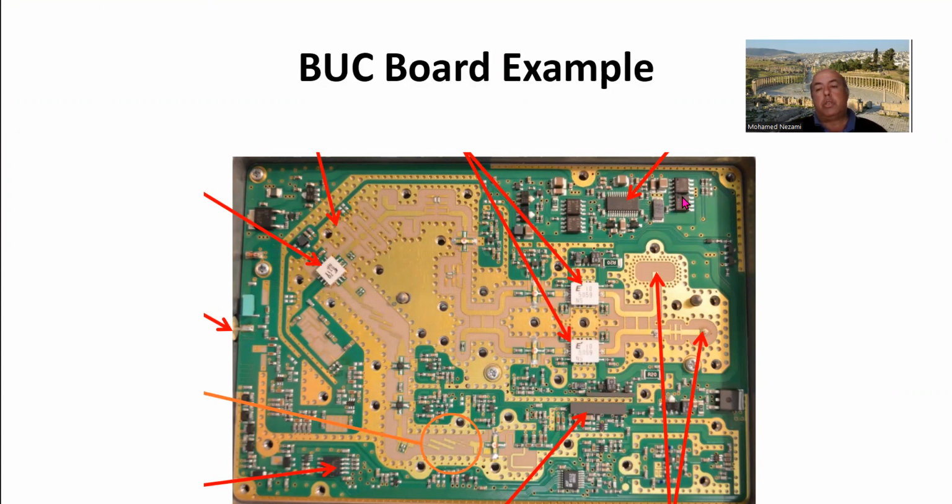So this is a system, and the other thing about this BUC example here, they've got the waveguide interfaces built in. The other ones actually are sideways, and so this is for both vertical and horizontal. And you could see that here's the stripline to rectangular waveguide interface on the vertical, and this is on the horizontal. But starting out way back at the IF, it comes in here using an F connector, and it goes into the DC. Of course, you extract DC.